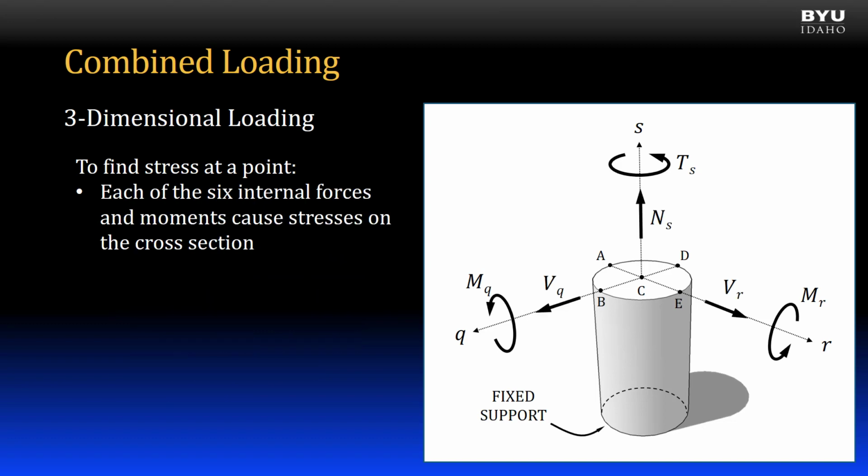Each of the 6 internal forces and moments cause stresses on the cross-section. The normal force and 2 bending moments, shown in red, cause normal stresses. The torque and 2 shear forces, shown in blue, cause shear stresses.